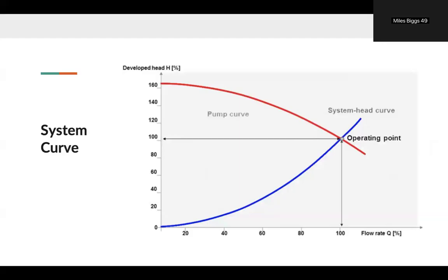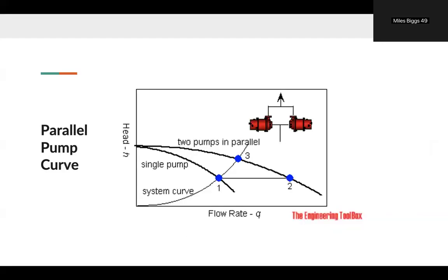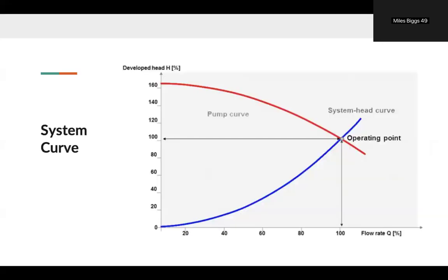And so a system curve. We have seen these in the past two pump curves. It's that line that's coming along the bottom. What that shows us is you're going to use that to select the pump. You match this with the pump curve to select the pump that you want. The intersection of the two determines the BEP, and it gives you the flow rate and head that you will need for your specific operating conditions.